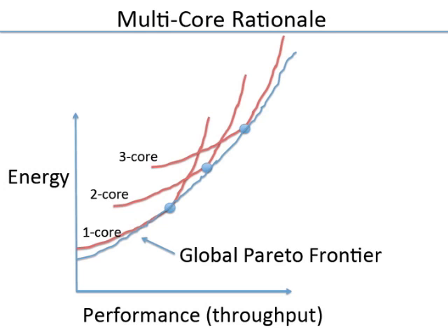At the extreme, you have just a sequence of flops. The flop has some embedded logic in it, right? So imagine that is the fastest you can do. A NAND gate with a flop. That will be a universal element in some sense. That will give you the highest performance frequency, if you could generate a clock which will drive that, but it will have an enormous amount of power because the clock is going to every gate. Every gate is a flop. Okay, so it will just be off the charts here. So it's not sustainable. So instead of that, you say, okay, I'm going to go to a 2 core.